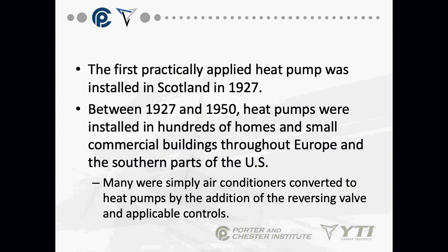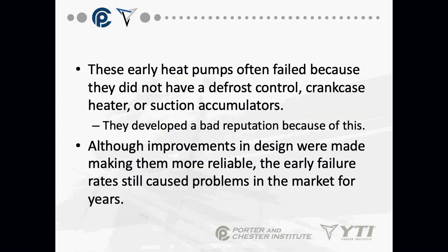We're going to talk very heavily about the reversing valve before the day is over. Okay, the reversing valve becomes very important. The early heat pumps often failed because they did not have defrost. Okay, in other words, once the outdoor coil started freezing up, it grew ice. When we grow ice on the evaporator, we start sending liquid refrigerant back to the compressor.